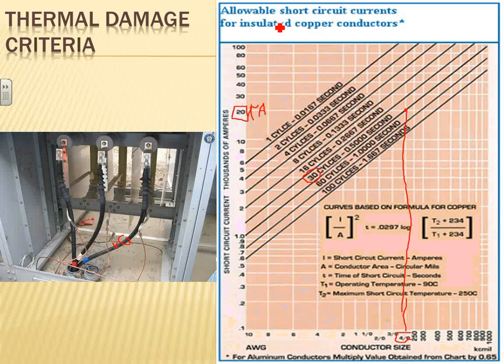Now, here's the irony: if you allow your circuit breaker to trip normally within one cycle, look what size conductor you need. Number 4. So you go from number 4 to 4-aught based on how fast your circuit breaker will trip on the medium voltage. So I threw this one, guys, to give you an idea.